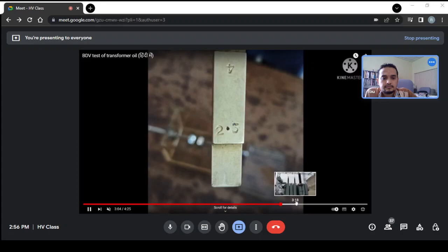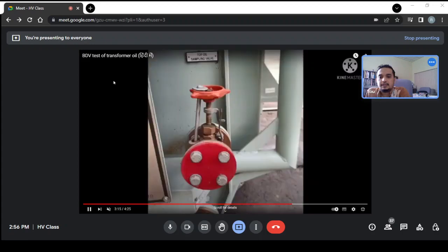So we will run, we will perform BDV. What is BDV test? Breakdown voltage test. That is, we call it as BDV. Okay, breakdown voltage test. I think the video here is kind of lagging.